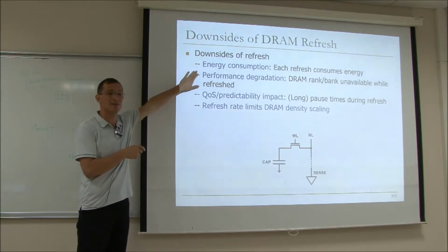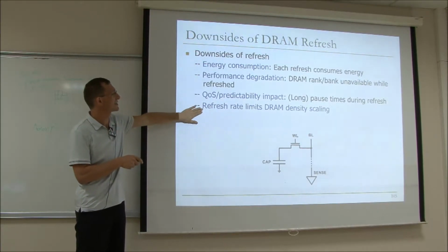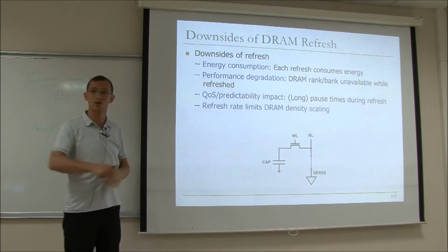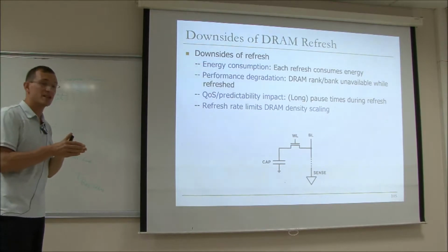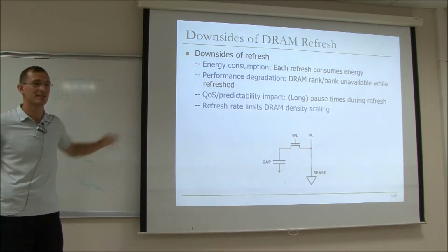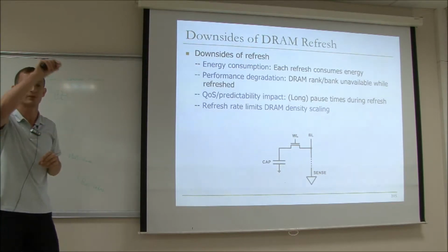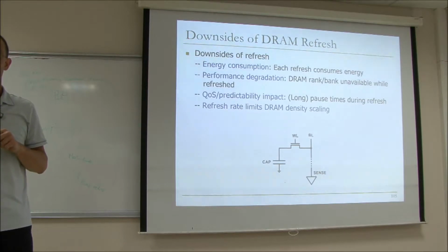Energy consumption: each refresh actually consumes energy. And I already told you this. Refresh rate limits DRAM density scaling. As we go forward, refresh will become a bigger problem because the refresh rate will increase, and also as we increase the capacity, the number of refreshes will increase. As a result, you get this exponential curve on the impact of refresh on latency as well as energy.